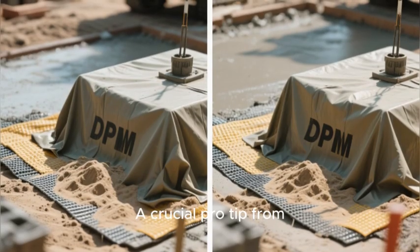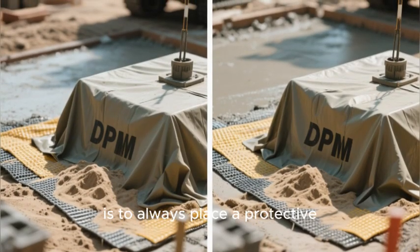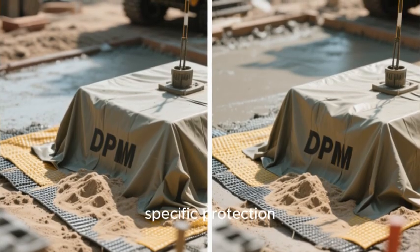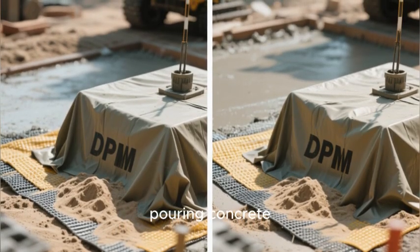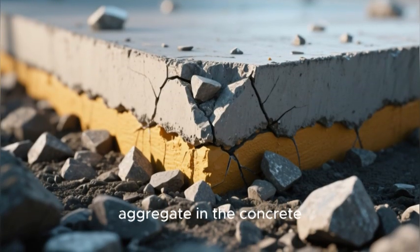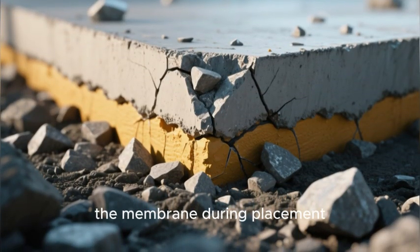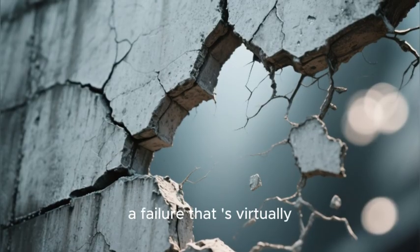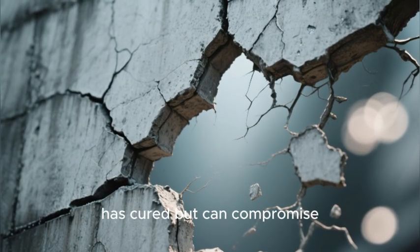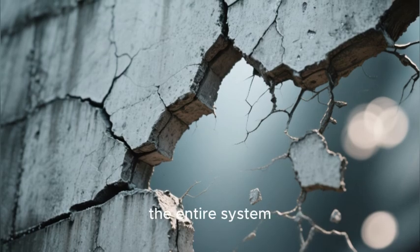A crucial pro tip from experienced site supervisors is to always place a protective layer, typically a sand blinding or specific protection mat, over the DPM before pouring concrete. This prevents the sharp edges of aggregate in the concrete mix from puncturing the membrane during placement and vibration, a failure that is virtually impossible to detect once the concrete has cured but can compromise the entire system.